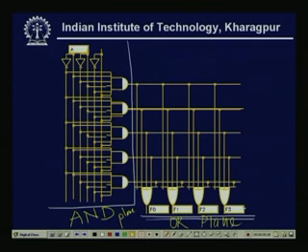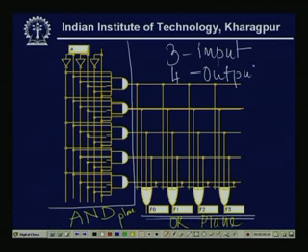So, why is it programmable? Because this is a structure for 3 inputs and 4 outputs, a programmable design. Any 3-input variable product term or minterm I can get by using this AND plane.